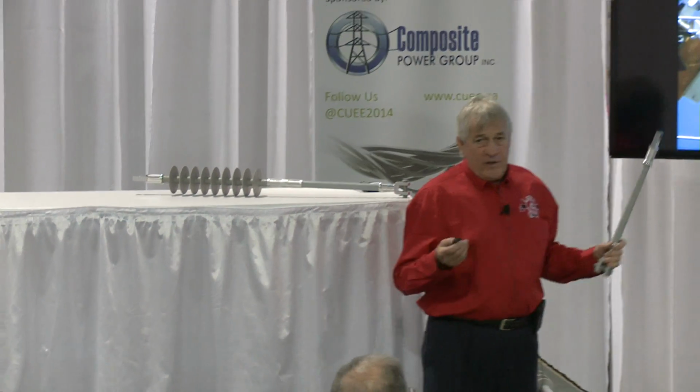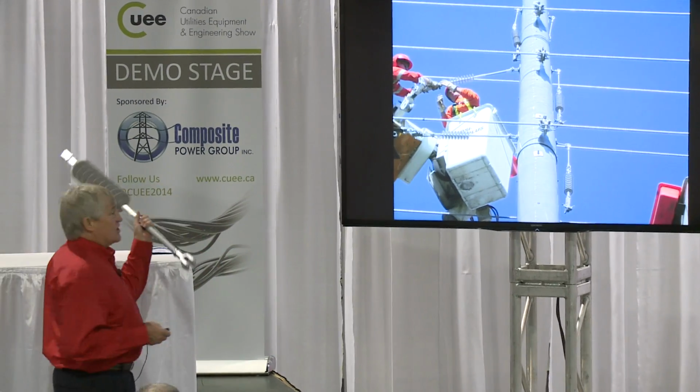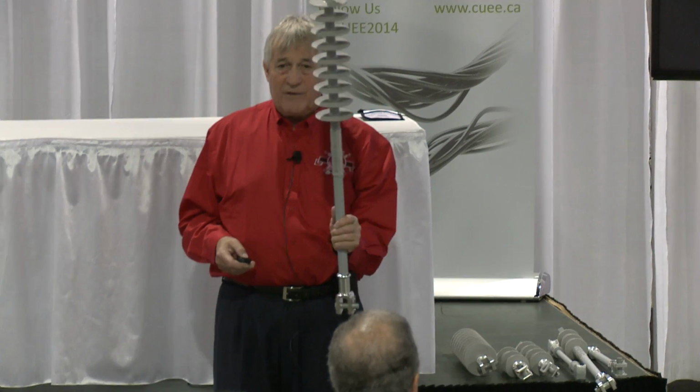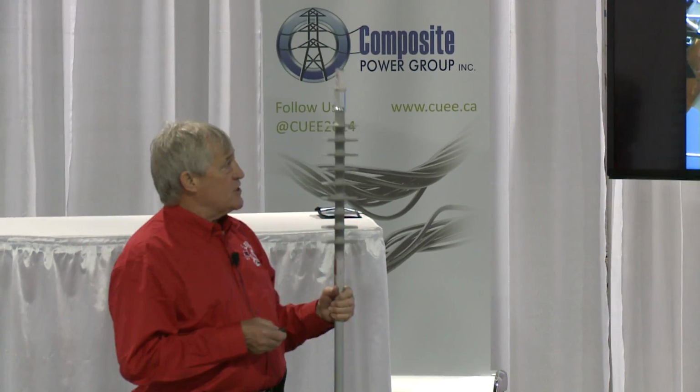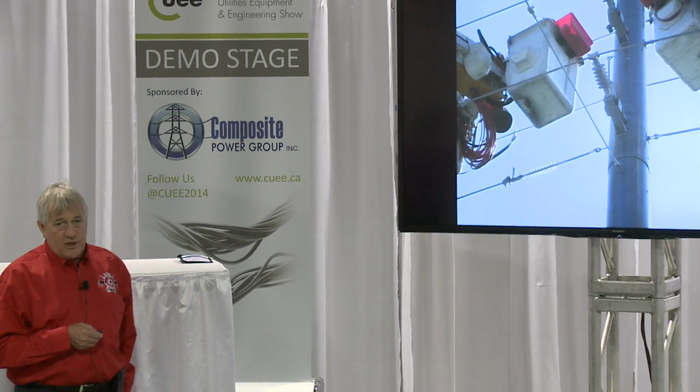The linemen, they do the dead ending the very same as they would normally. The linemen generally like the extension insulators. You know, they stand up in the bucket. They're nice and easy to use. You don't have a lot of cotter keys or cotter pins to work with. Doing the dead ending through the same procedure. There's the bottom circuit done.